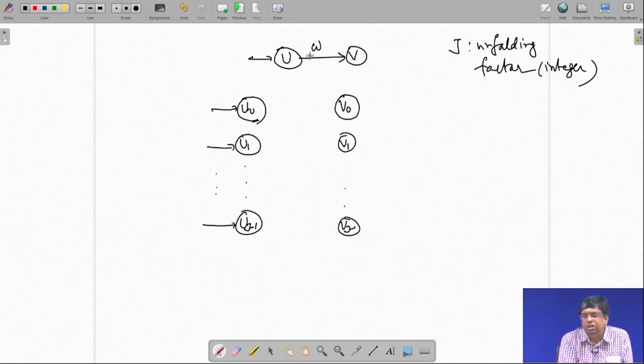This delay W is with respect to the original input clock, the faster clock. But when you parallelize, the system will be working at a slow clock. So, it will not be the input clock; this is the original DFG with respect to the original input and output rate, with that rate there is W number of delay, but now you are parallelizing, so the system will be slow, input will be faster.